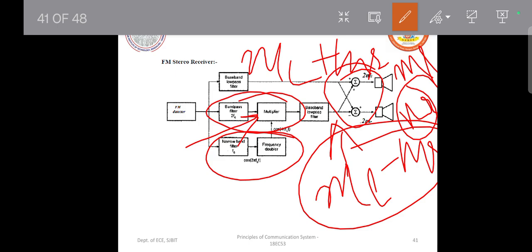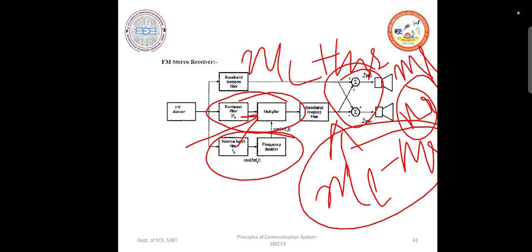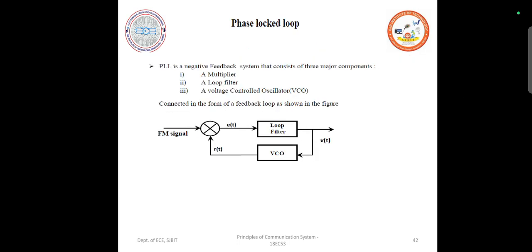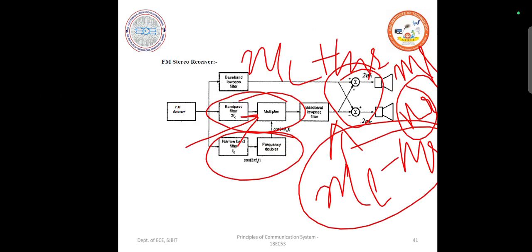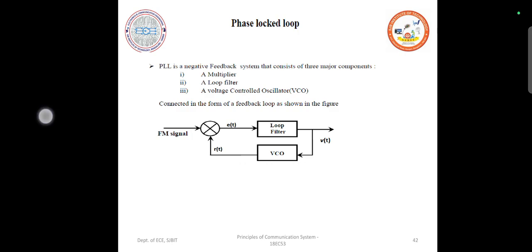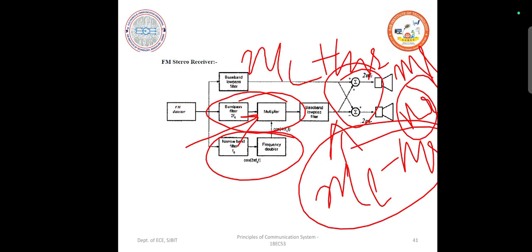So I multiplex it, send the signal through the frequency modulator, receive it, perform FM demodulation, and then perform this so that you can get back your individual signals. So this is about stereo multiplexing. Are there any questions on this? This has a lot of applications. We can better understand when we write equations at every stage. The equations will clarify all our questions relevant to these things.